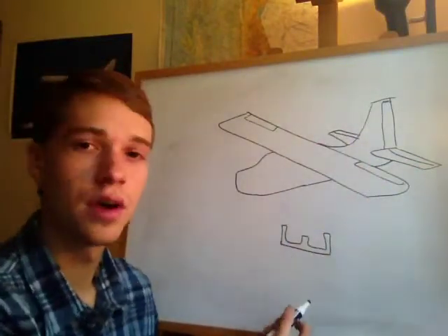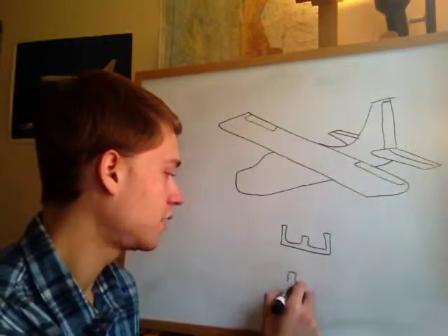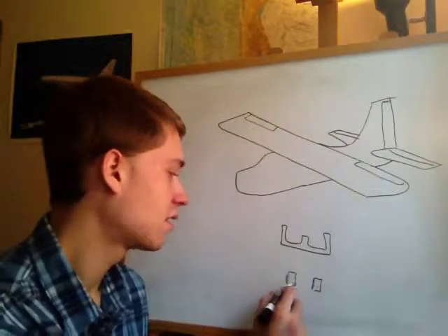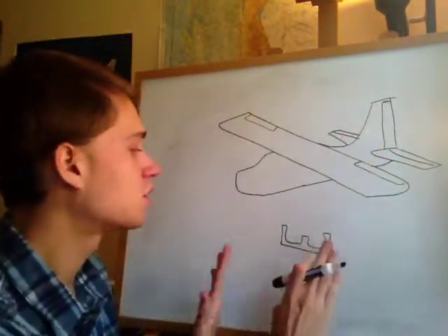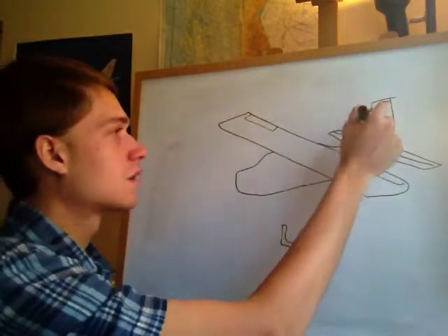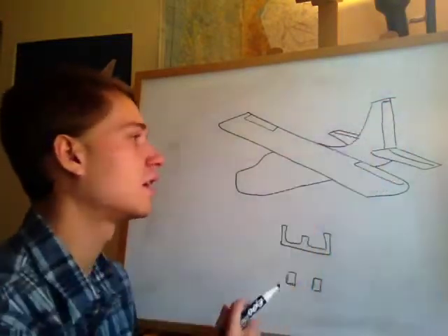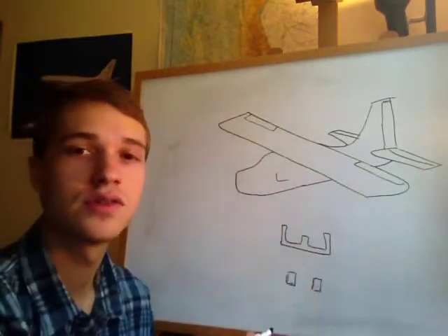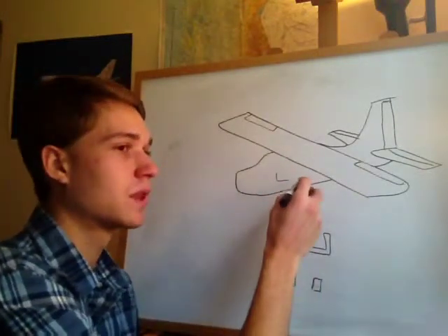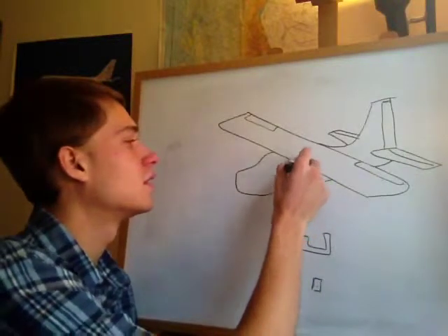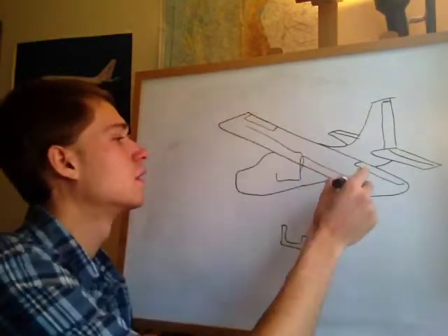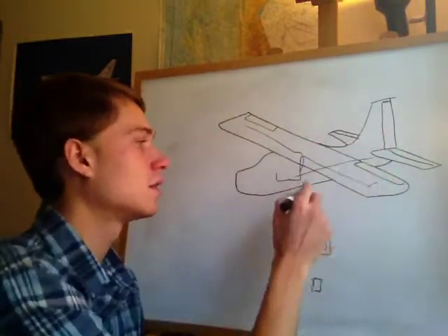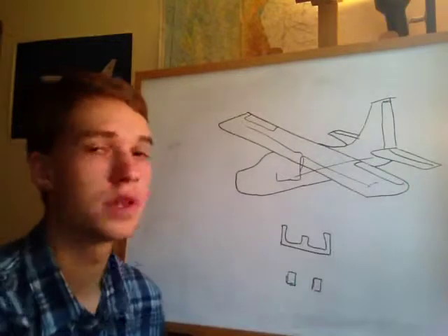So that's our control yoke, and then you have down here where your feet are, you have 2 pedals, and no, this is not gas and brake. They actually are hooked up to the rudder. And so when you push the rudder, right rudder, left rudder, that will deflect the rudder either direction. And these are all hooked up by mechanical linkages. You'll have like these cables and pulleys and a system of that, and that'll be hooked up to actuating rods, and that's how the yoke and the rudder pedals are hooked up to the actual flight controls.